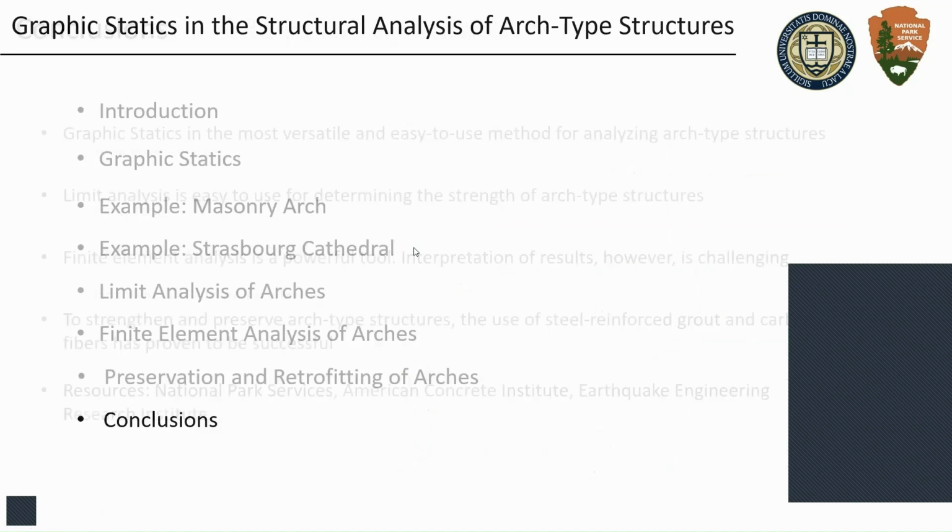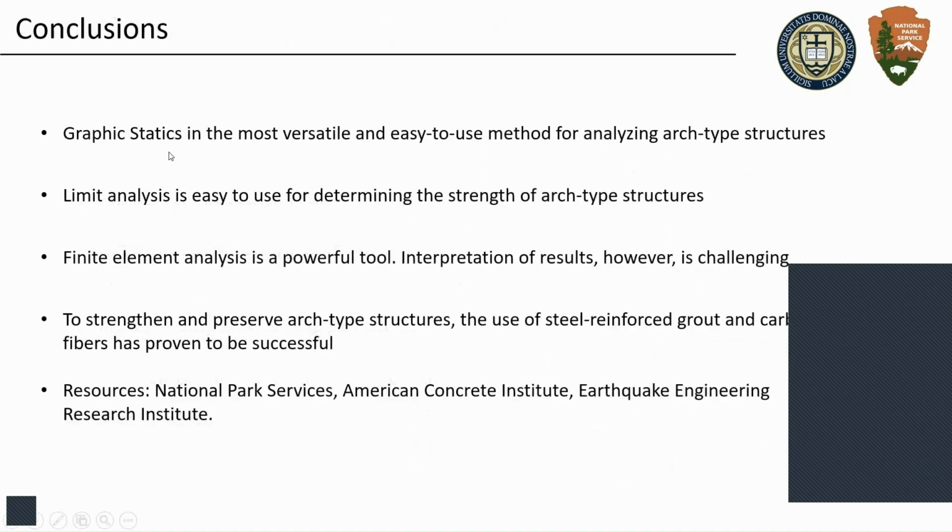Let's go to the conclusions. So keep in mind that graphic studies is probably the most versatile and easy to use method for analyzing and designing arch-type structures. Limit analysis is easy to use and is very powerful for determining the strength of arches. It gives you the exact solution, by the way. Finite element, I mean, it's a powerful tool, no doubt about it. Interpretation of results, however, is challenging. And keep in mind, it can't reproduce cracks, and that's a huge shortcoming, or can't represent cracks reliably.